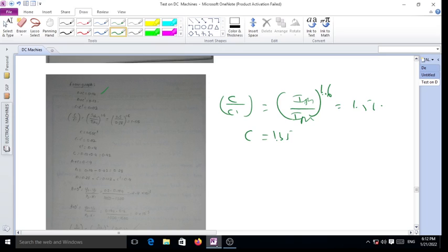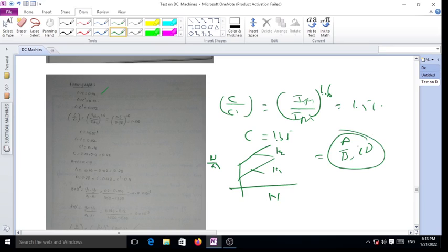These values will be found out by drawing the graph at different excitations. For the W by N value and speed, we get straight lines, and we find out the slopes. By finding the slopes, we get the K1 and K2 values, and from those the values A, B, C and D. This is found out using the separation of losses, that is, by conducting this test.